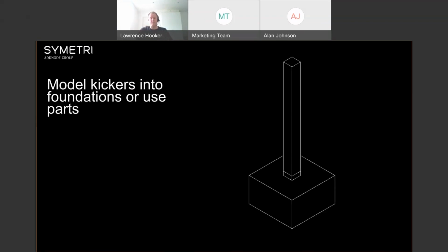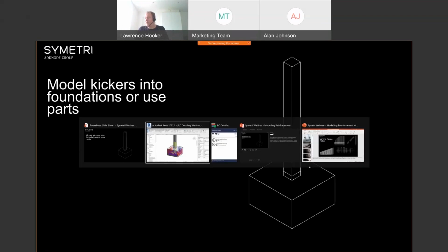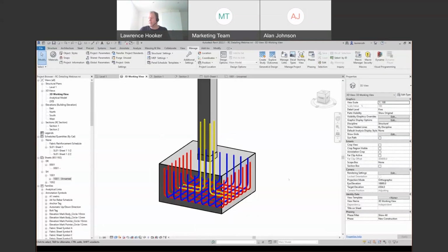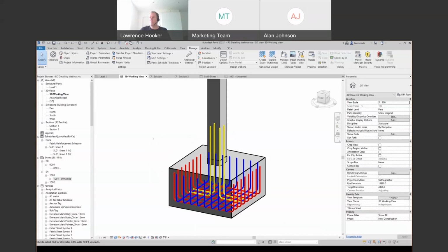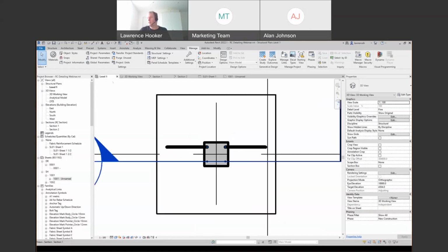And Revit fully supports the reinforcement of parts. So of course you can have a big RC wall or a big slab, break it down into parts and reinforce those according to those part divisions. Of course, if you've got things like expansion joints and so on, the parts would also accommodate that as well. Okay, so a couple of little tips and tricks you've just seen there. What we're going to do is now go back into Revit and we'll have a look at placing in some reinforcement bar into a slab this time.